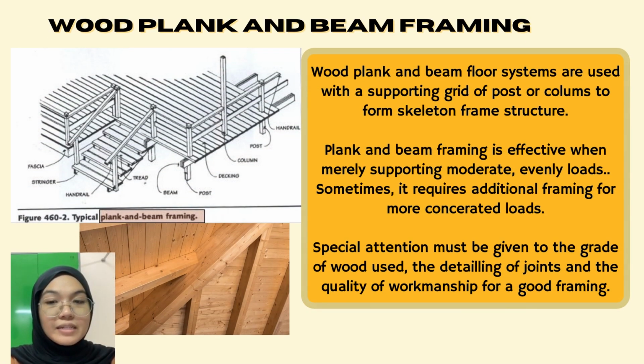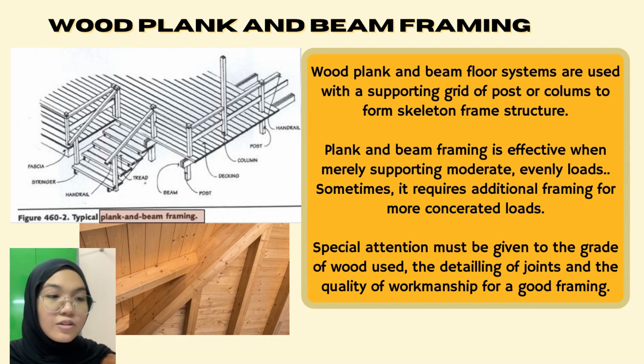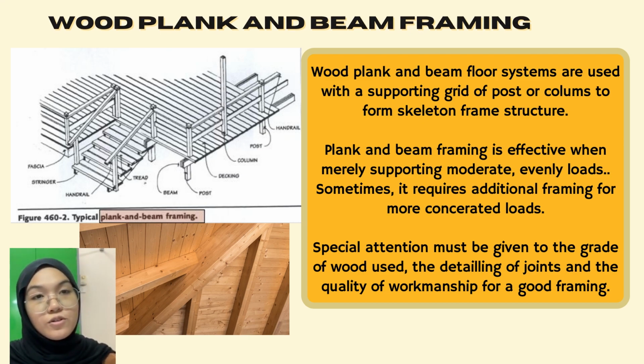The next system is wood plank and beam framing. Wood plank and beam floor systems are typically used with a supporting grid of posts or columns to form a skeleton frame structure. They use larger but fewer structural members that can span greater distances, translating into potential savings in materials and labor costs. Special attention must be given to the grade of wood used, the detailing of joints, and the quality of workmanship for good framing.